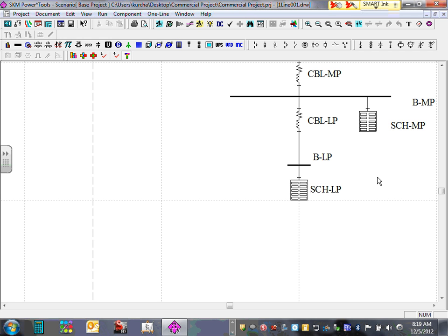Identical copy. The difference between copy and cloning: copy, guys, will only copy either data or symbol. Cloning will copy the data and the symbols. Clone basically makes an identical clone of that particular component. So I'm going to show you cloning, very simple. So box in, hold the left.